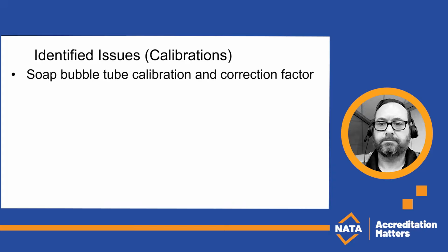So calibrations. In-house calibrations, metrological traceability, that's the cornerstone of our ISO 17025 accreditation. So soap bubble tube calibration and correction factor. Has it been calibrated sufficiently as glassware? And are we applying a correction factor when we're using the soap bubble tube?